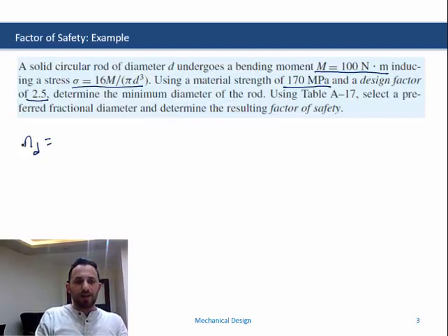So we know that the design factor is equal to the strength over the stress, and this is equal to S over 16 bending moment over pi d cube.